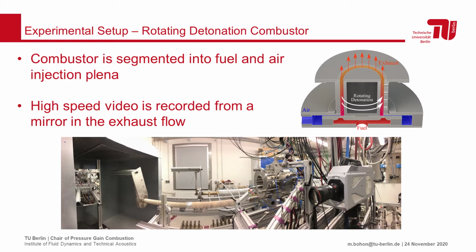A cross-section of the device is shown in the figure on the top right, where air and fuel are injected separately and where the flame is stabilized at the head of the combustor. A common diagnostic in RDC research is to visualize the propagation of the detonation wave using high-speed video. We accomplish this by imaging the aft end of the device through a mirror.